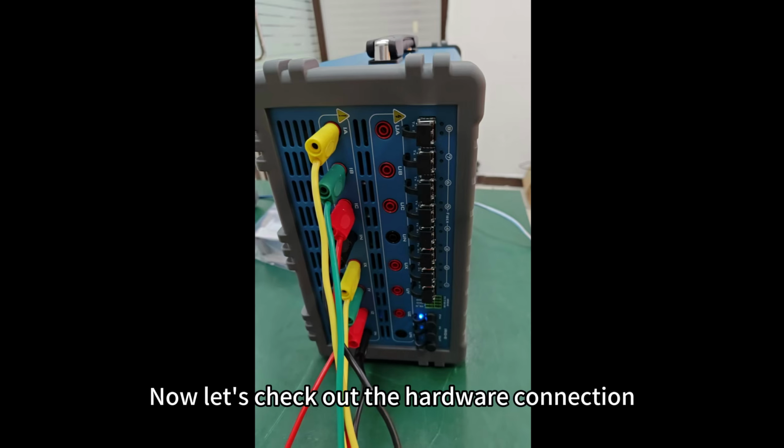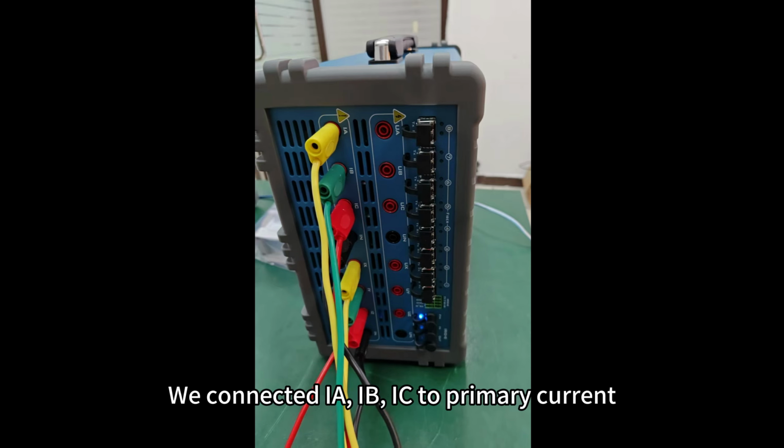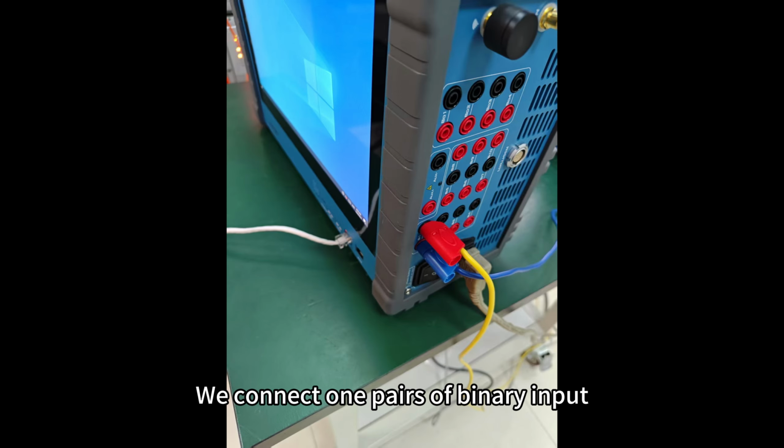Now let's check out the hardware connection. We use KF86P for differential test today. We connected IA/IB/IC to primary current, IX/IY/IZ to secondary current. We connect 1 pair of binary input for trip signal capture.